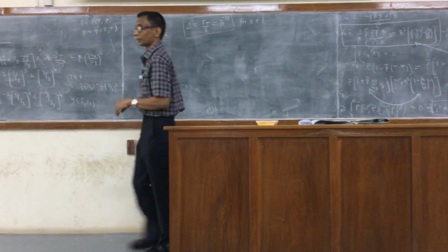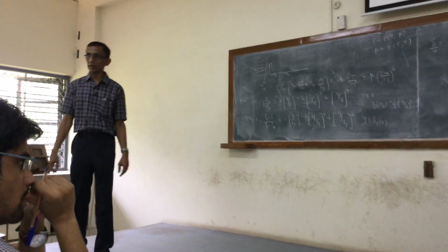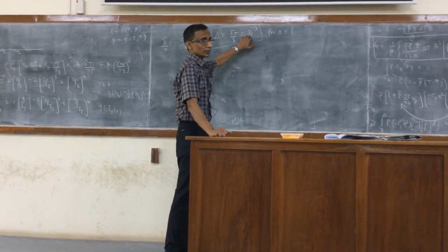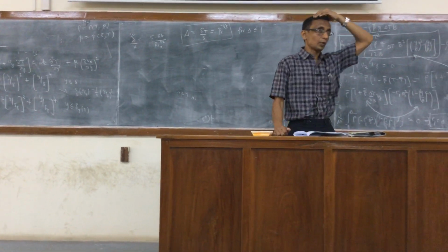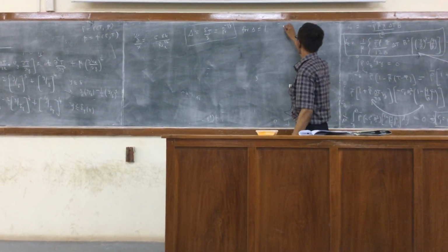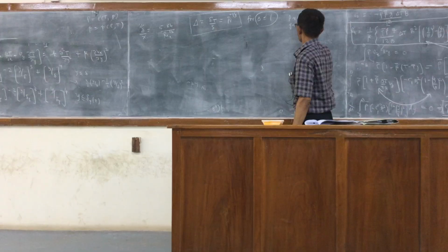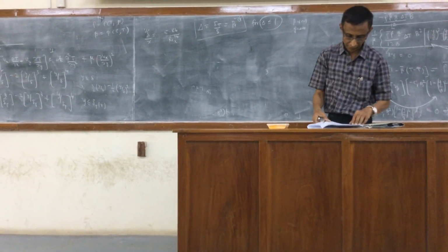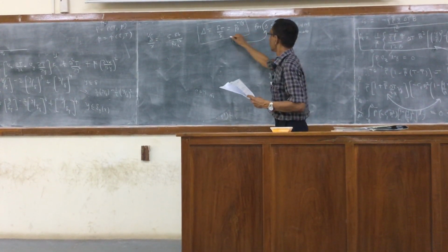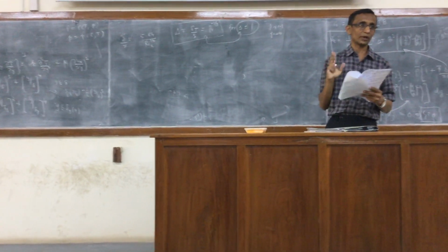And so the thermal boundary layer will be more or less the same as the hydrodynamic thickness, whereas for liquids, the Prandtl number will be much greater than 1, right? It's the hydrodynamic boundary layer that will be larger than the thermal boundary layer. So because this limitation is there, I don't know how we can extrapolate this for other cases. But this is accurate for delta T less than or equal to delta, and for other cases it may give a rough idea. That's how we have to take it.